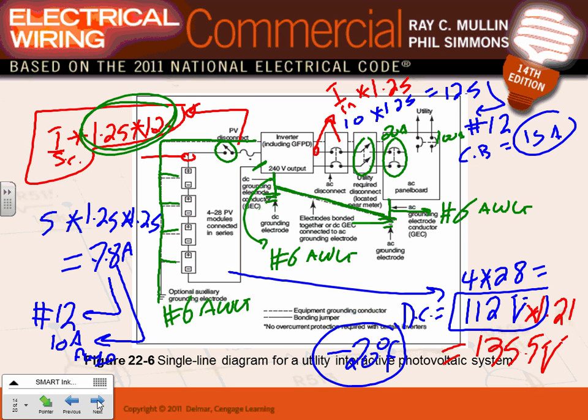Any comments? Who cares? The question here, Jeff, is who cares, right? Your conductors have to be rated for a certain voltage, typically 600 volts. What if you build the system and in summer the voltage is within 600 volts, but in the winter, because of the multiplier, the voltage exceeds 600 volts? If it exceeds the insulation rating, then it becomes dangerous. The voltage can run away from the conductors into the surroundings. Your insulation is not rated for the voltage. That's why it becomes a big deal.